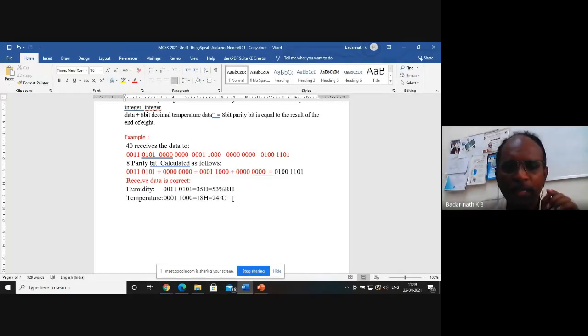So I'll be using a library which is already available for doing this. It's not required for you to write a program, but of course, when a library is not available, you should understand that using a datasheet, I can always develop the libraries on my own. That is the purpose of learning microcontrollers at the lower end, because many times your job is to develop the libraries. How do you develop them? You should read the datasheet, know the timing, and do the low-level timing implementation. We will see that in 4 and 5, where we will address certain library development.